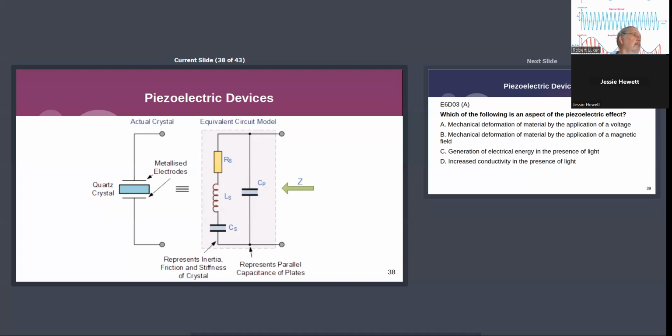They have a bunch of crystals in ovens, little oven devices that maintain a very stable environment. Yeah, that's what I said. That's one of the problems with a lot of radios, that there's drift on the reference oscillator, and you turn it on and wait a little while until it gets up to its ambient temperature.